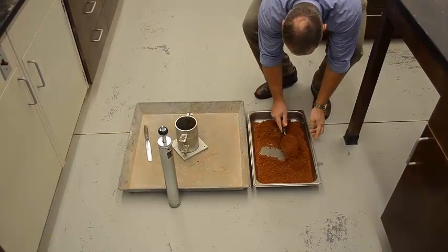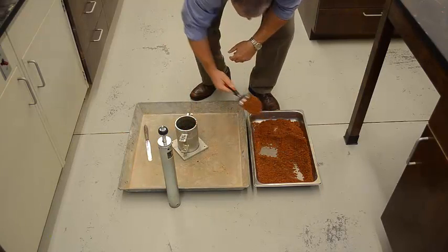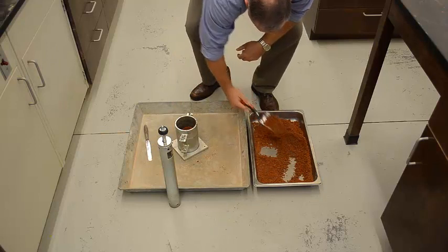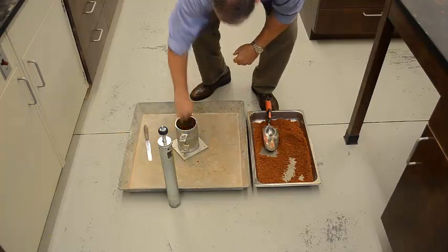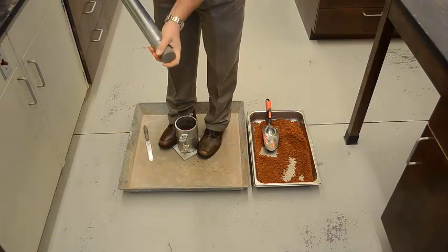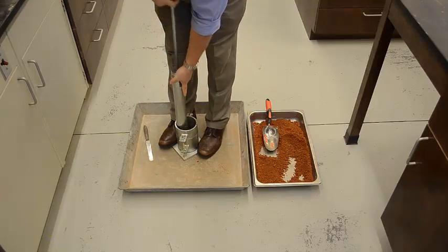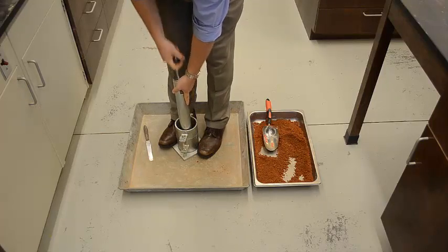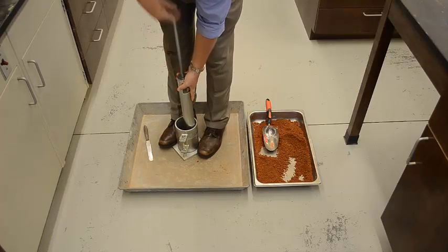Okay, then I start the process over again, where we start with a bottom lift, about halfway or so, and you'll notice that the soil will start to behave a little differently the more water you add. Obviously make sure your hammer is clean, but this will be a little bit different than the last point you did, and then the next one will be a little bit more wet, and then it'll behave a little bit differently. And like I said, soil behaves differently depending on how much water is in it. That's why we need to understand those behaviors.